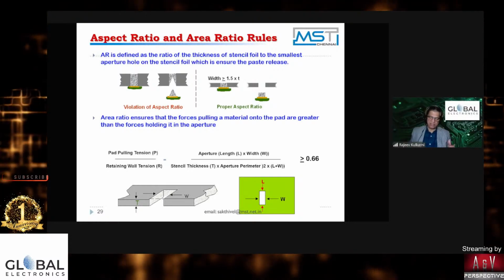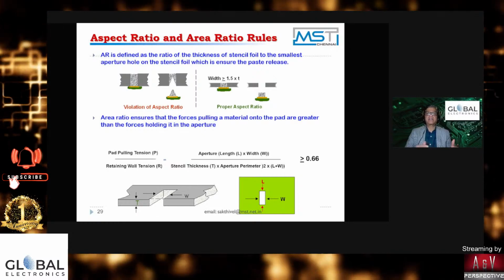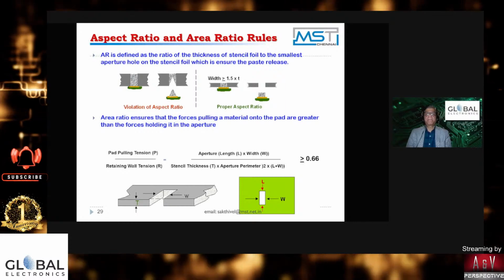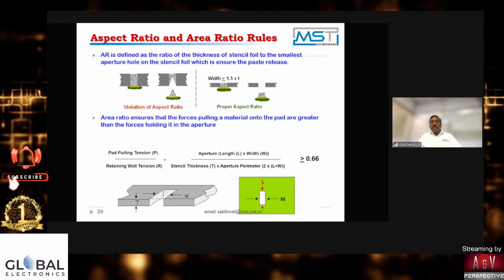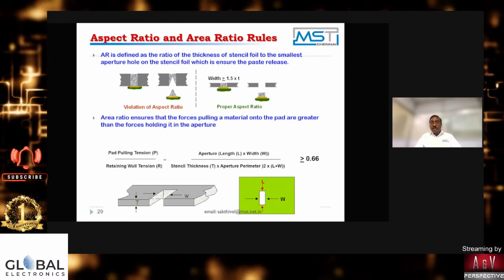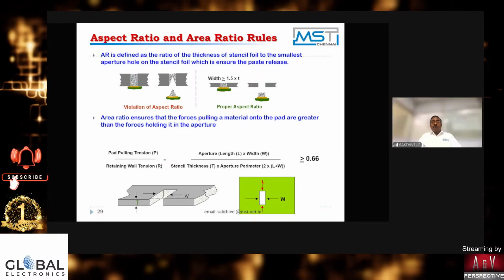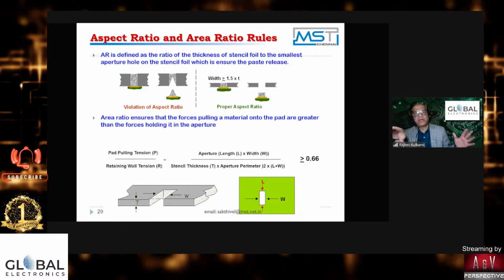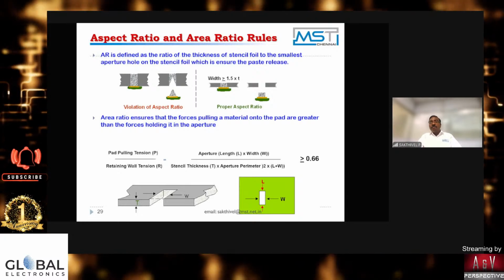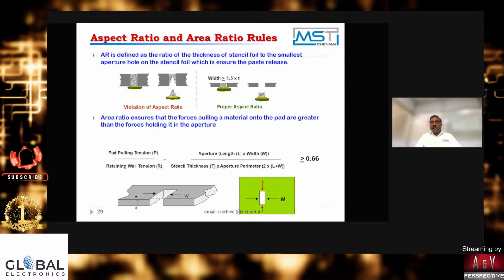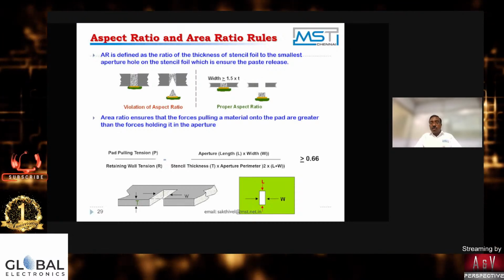So it is a process which you offer to the customer after the laser cutting of the stencil. After the laser cut, we do the deburring, and we have all this equipment, CVD, chemical vapor deposition equipment. It's bigger in size, like a big chamber. It is done in a vacuum chamber, whereby the foils are loaded in the machine. It coats on one single side, the PCB contact side.